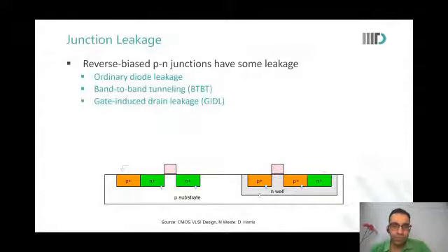Yes, sir, but due to the stack effect I am getting a reduction in leakage. Earlier in the slide you were saying that 95 are basically high VT devices, but for the digital circuit I can go for low VT then. Yeah, it means that you will have to use more transistors if you do not go to high VT. If you only use stacking to reduce leakage, then even for an inverter you will do a stack of 2 NMOSs and a stack of 2 PMOSs to reduce leakage. Yes, sir. You waste area. Instead, you use HVT devices.